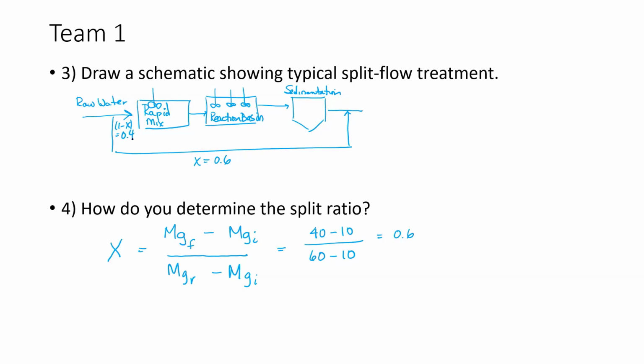Now, pH of this water is typically between about 10.3 to about 11.3. We can't distribute water at that pH. It's highly corrosive. It would feel kind of really slimy. So we have to reduce the pH.